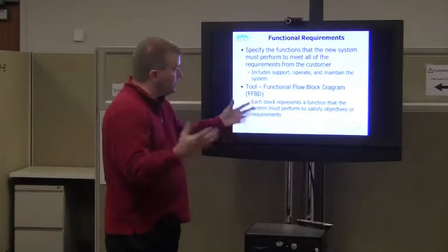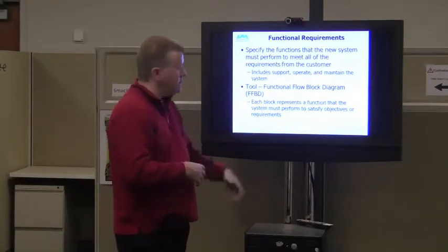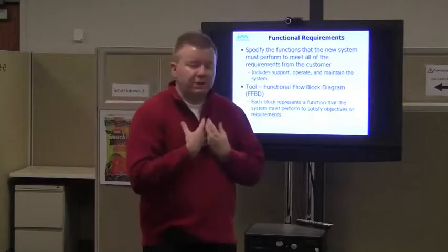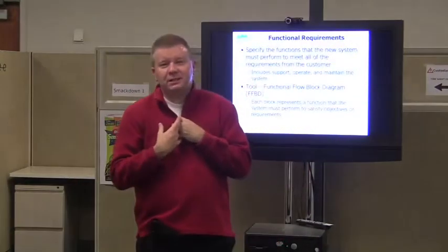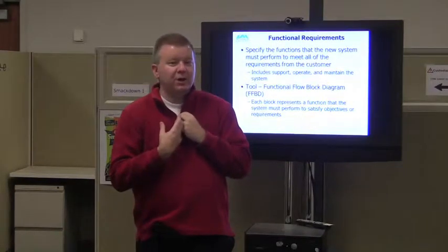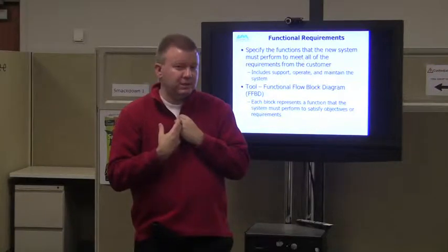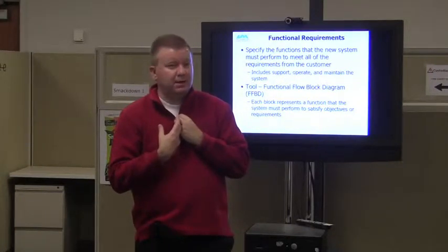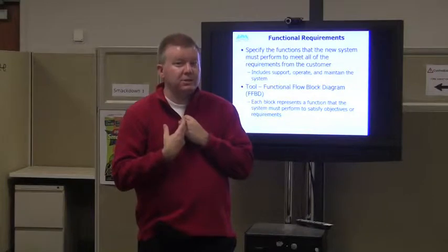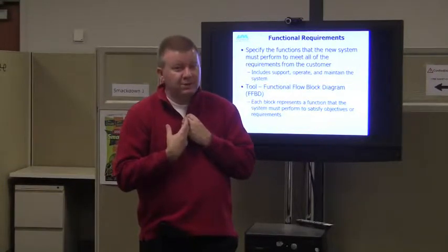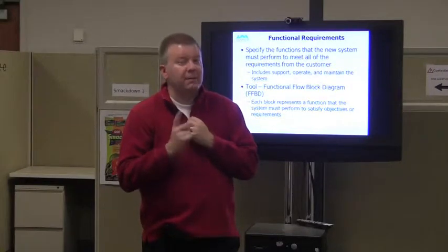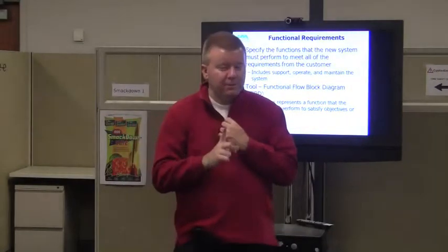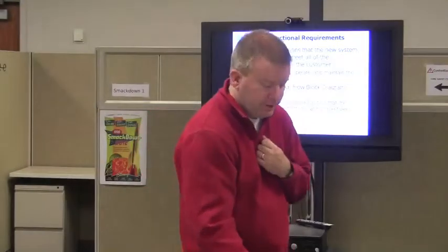So each block represents a function that the system must perform to satisfy the objectives of the requirements, right? And this is a function. This is not the solution, okay? These are actions that the system needs to take. These are not solution-based. And you gotta remember that, because most people, when they start this process, they have a solution in mind. You don't want that, because then once you create the functions and you create the requirements from the functions, you get the solution that you had in your mind. And maybe it's not the best one. So you got to remember that when you do this. It's a very hard step to follow.